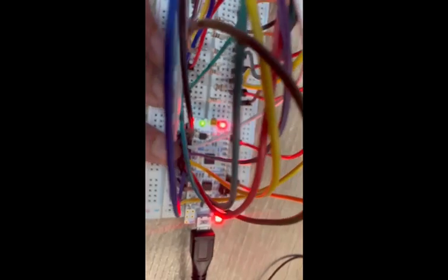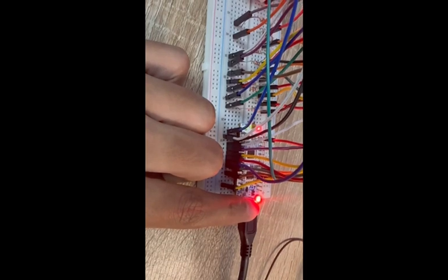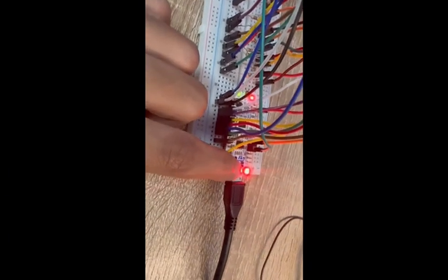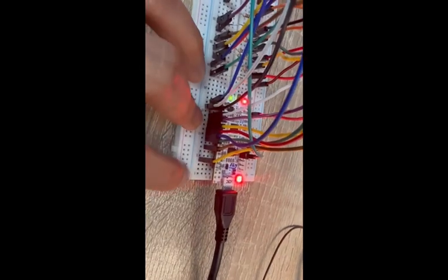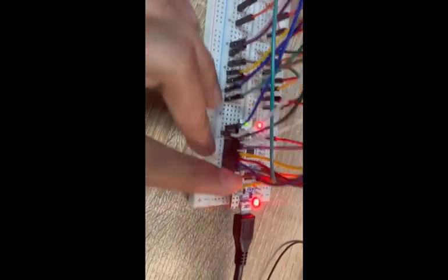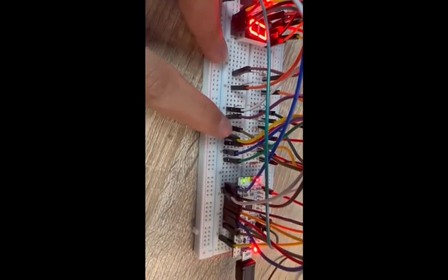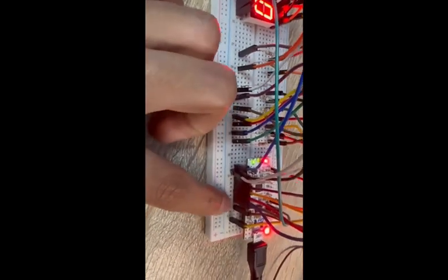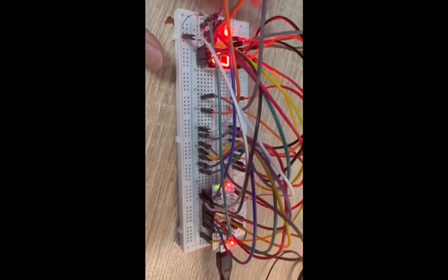Because we use GPIOA, I use A7, because at the STM the port is at A7. So our C, the brown wire, is put at number 3, which is 0, 1, 2. So our 2 is at A7, and the others are the same. So that's all from me.